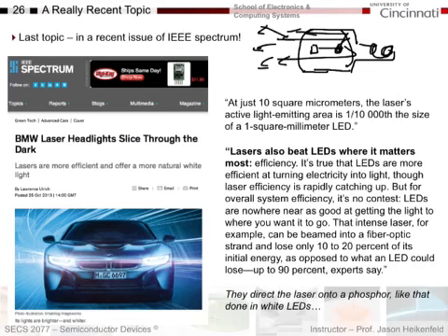So why not just use a blue LED to excite the phosphor? Well, it turns out that when you go to really high power lamps, lasers become more efficient than LEDs because they send the light out in a certain direction. As we know, all the photons go in the right direction, which is the right direction to excite a phosphor and get light emission out of this bulb. So when it comes to really bright bulbs like you need for the headlamps of a car, we might see lasers beating out LEDs because of their higher potential efficiency specific to this type of application.